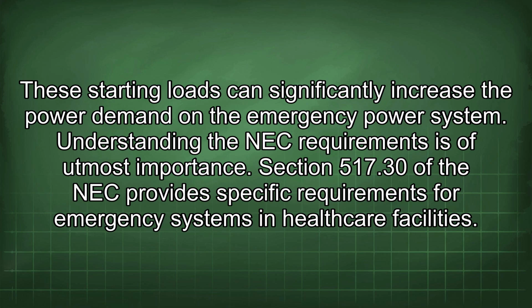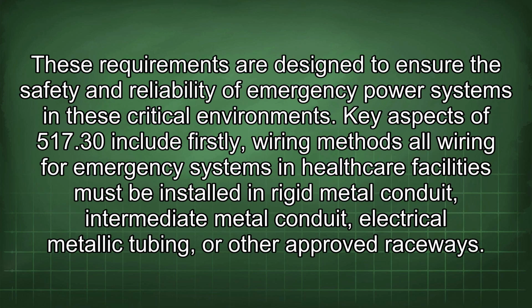Understanding the NEC requirements is of utmost importance. Section 517.30 of the NEC provides specific requirements for emergency systems in healthcare facilities. These requirements are designed to ensure the safety and reliability of emergency power systems in these critical environments. Key aspects of 517.30 include: firstly, wiring methods.